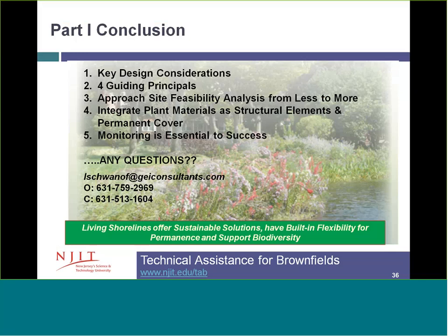Start first with what can you do with less rather than more in terms of structure. If you can consider that, you may have a successful living shoreline that you can incorporate into the shorefront instead of a conventional practice that has very little ecological and coastal benefits associated with it. And again, monitoring is essential to success.